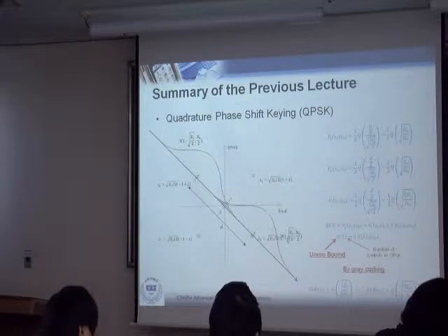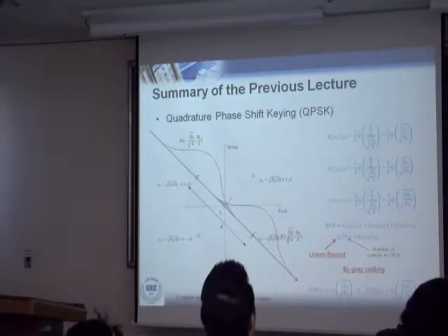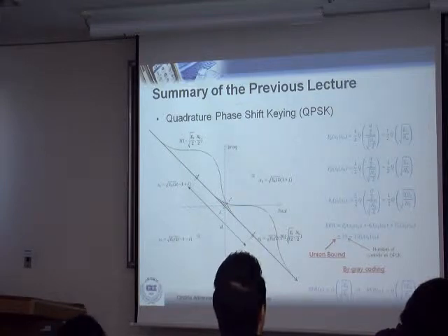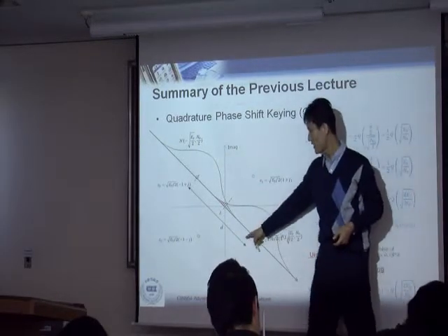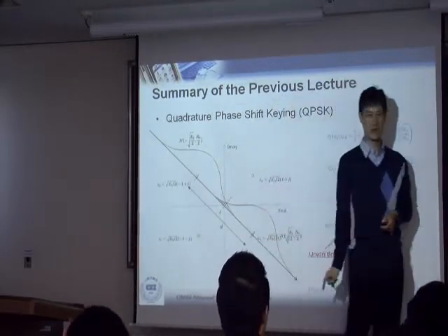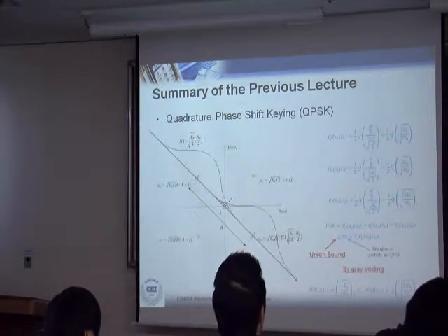So this is where you do a QPSK encoding or modulation, and this is where you do a demodulation. So once you do the modulation, you change bits to the symbol. Now right here, after modulation, you are transmitting a complex value, one of these four, right?